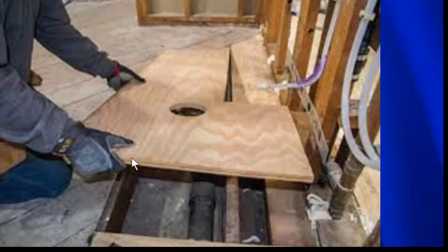So when they did this, if they had replaced all the nails, let's say they put a nail every 2 inches along this floor, and then when they put the piece of plywood in, they would have done the same thing here. So this would have had a piece of plywood that extends across here, and then there would be a nail every 2 inches into the plywood, a nail every 2 inches into this board right here.